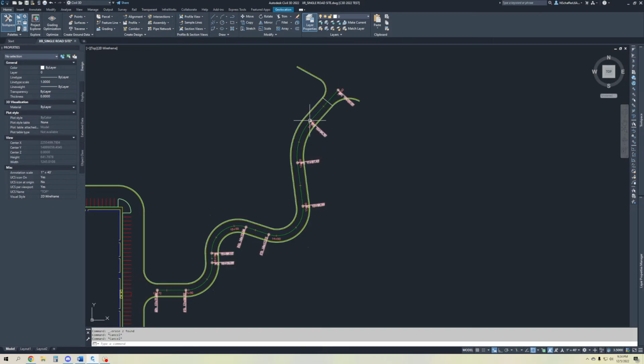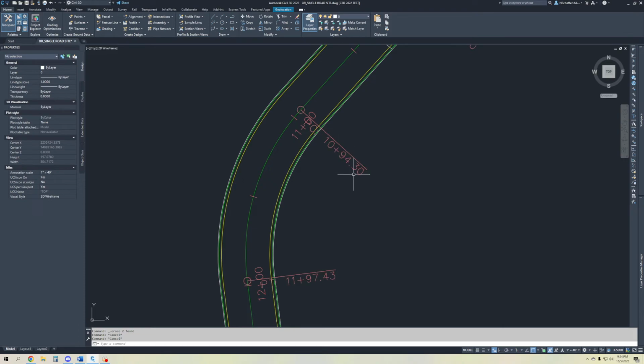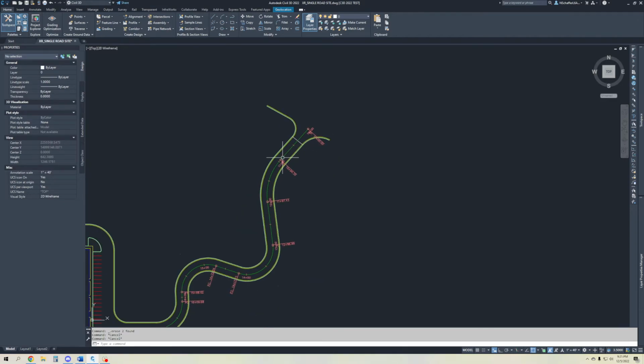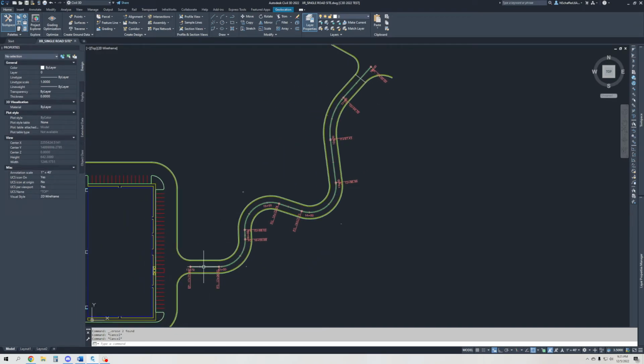We can tell them how long this is going to be. So it'll be 94.3 feet going at whatever angle and bearing that is. And they can mark this point. And then we can tell them the radius of this curve and where this point is. And they can now create this curve. So that way they can go through and create this exact road and give us the exact center line so that the contractor can come in and build that road based on what we have given them here. So that is one use that you can do, and it's a very common use.